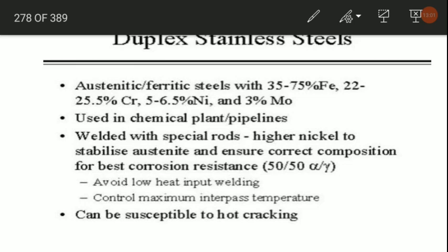So as you can see, there are different characteristics and properties of stainless steel, and mainly talking about weldability, the austenitic, precipitation hardening and duplex stainless steels have the highest weldability among the different stainless steels. Okay, so these are the things you have to know about when welding of stainless steel comes into the factor.